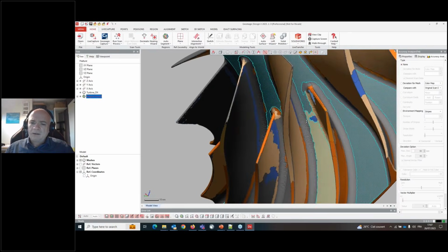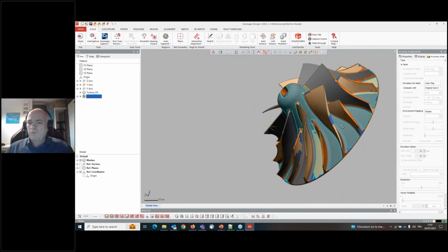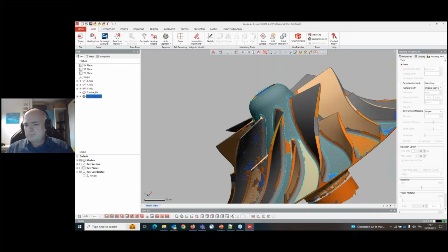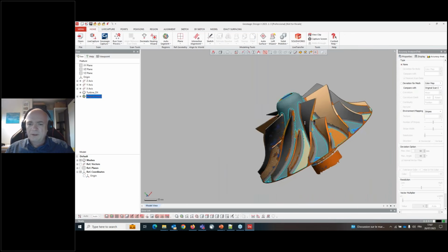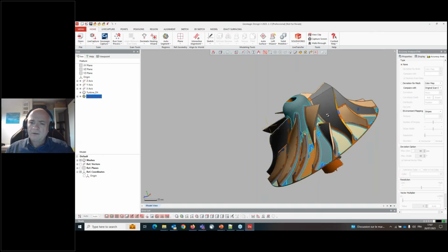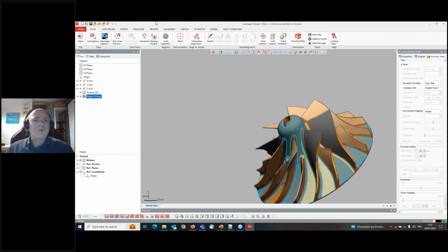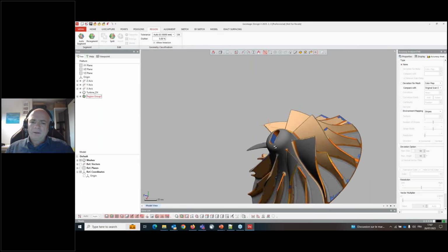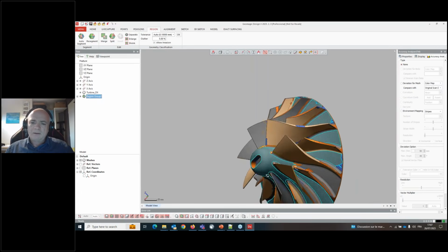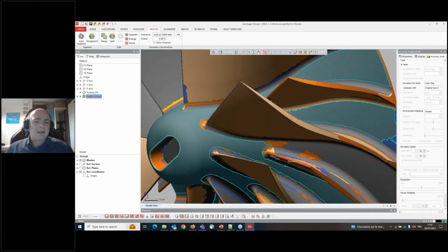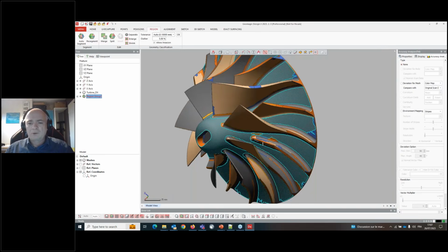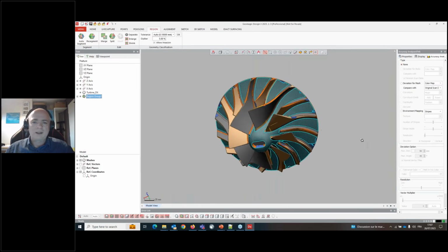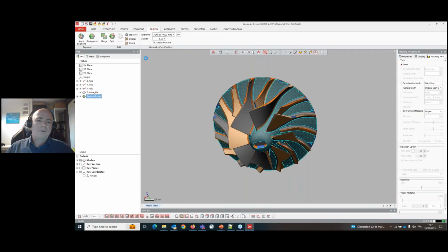It's not really necessary, but I prefer to work that way, because like that I can see what data I used in the software. So here I selected all the regions I would like to add. And then from that, I will just go to region and merge. So the software will merge all the regions together in order to get the main top area. If you forget one region, like here, you can do the same process, add those regions. Even though I missed that one, I don't really care. And I will again merge all those regions.